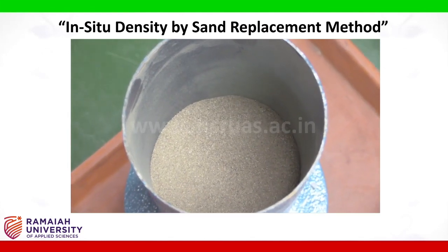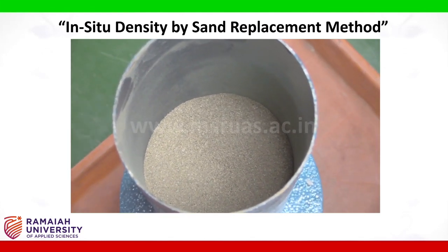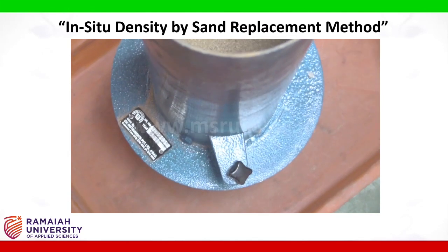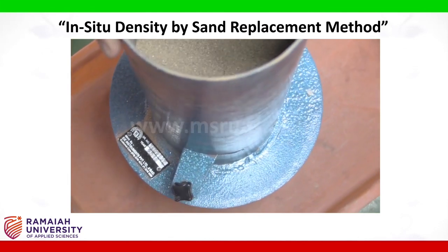Once the movement of the sand stops, close the valve and weigh the sand pouring cylinder.